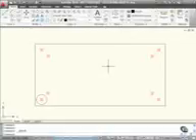Okay, so let's now look at copying objects. The copy command is very similar to the move command. In the previous example, we looked at moving the circle inside the rectangle. We moved it to different node points, turned the nodes layer off, and utilized object snaps and object snap tracking as well. We're going to do the same, but this time when we copy, the original stays where it is.